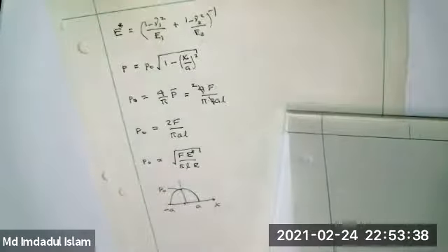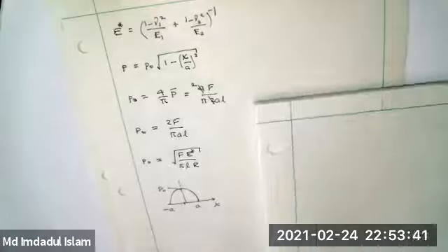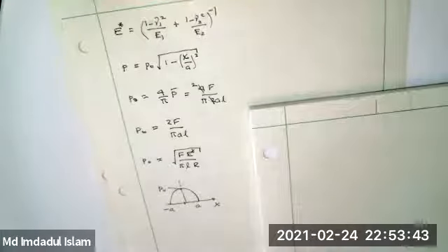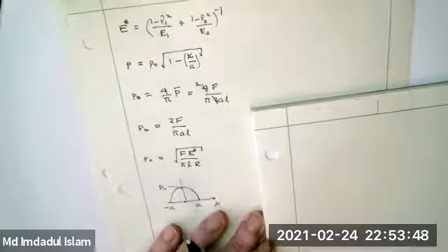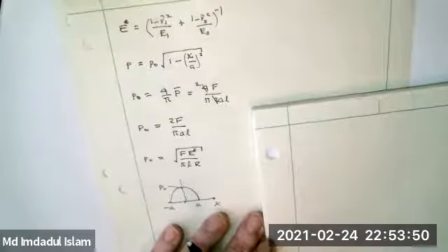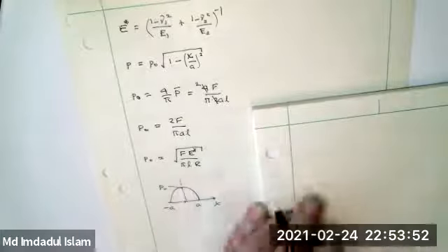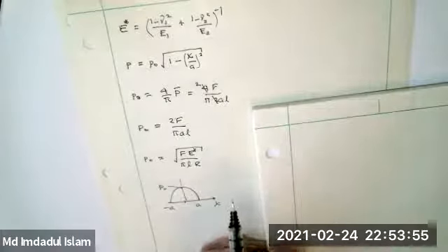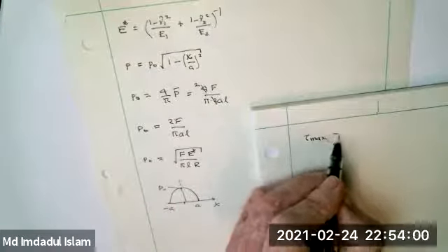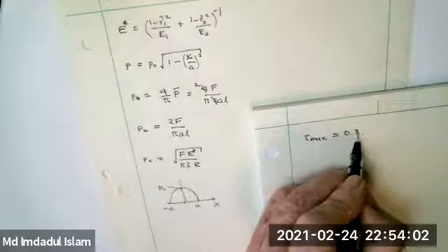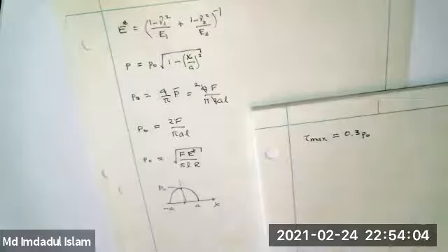But it's important because a lot of failures occur with contact stresses. And one of the things that guides failures, you're normally talking about metals. And metals, we're going to talk about this more later on, but they fatigue when they start to yield. And that's driven by shear stress, not normal stress. And so tau max is only 30% of P naught. That's because the stresses right under the indenter are all around compressive, and so when you take the differences between the two and divide by 2, you don't get much.